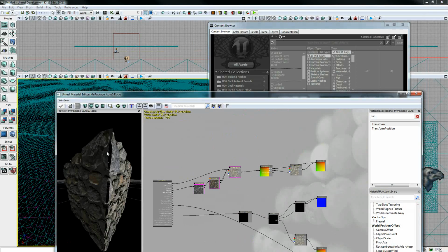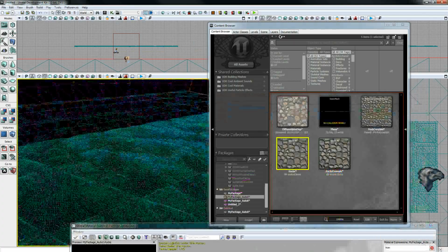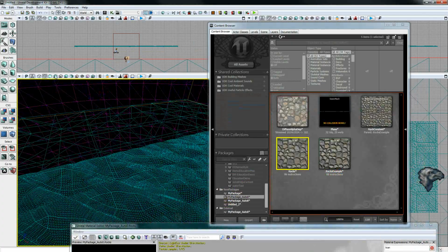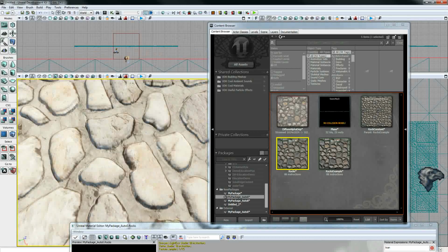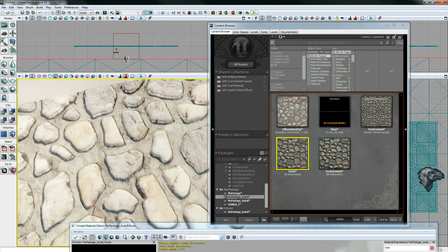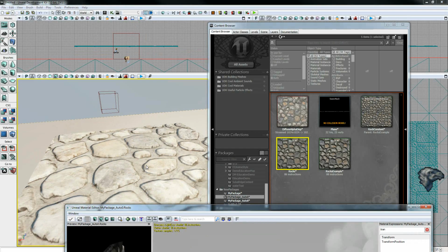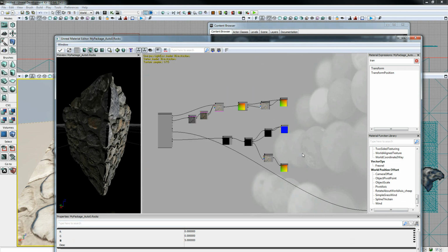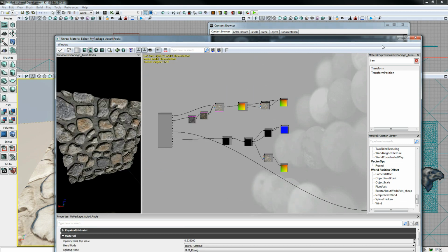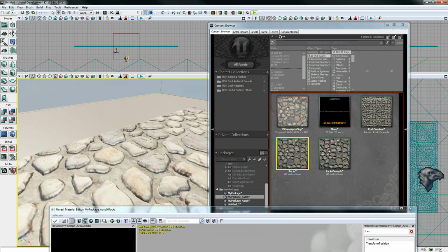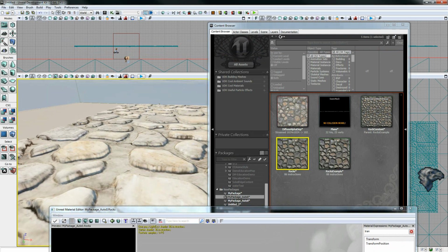And as I move around, if you check it, obviously the amount of tessellation changes as you get closer and further away. And so what that means is as I get closer and further away, the mesh will sometimes ripple. So what this allows me to do is you can use less of a displacement and still supplement that with your bump offset, and you get a pretty good looking result. Alright, so that's how you make tessellation work, and that's how you use DX11 in this case.